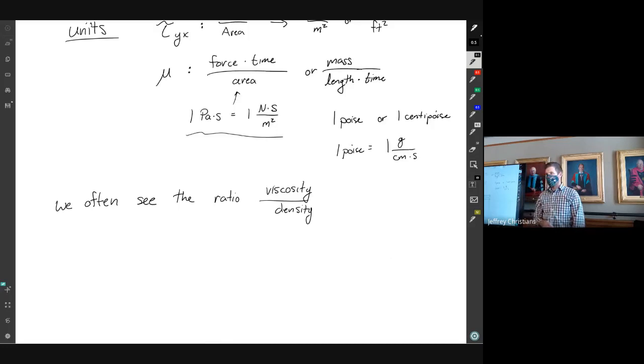When you're talking about flow, viscosity is like friction forces. Density is related to inertial forces, inertia. So if something's moving and viscosity is restricting the flow, the inertia is trying to keep the flow going. So if two things have the same ratio of viscosity divided by density, in a lot of cases they'll behave the same, because you have the same resistance to flow, inertia ratio.